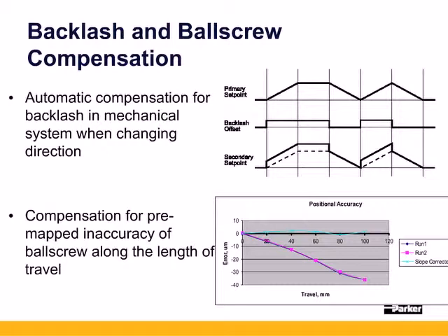So the ball screw profiler is a table for compensation for the periodic and linear errors, allowing higher accuracy positioning without the additional costs of linear encoders or the complexities of a secondary feedback. In addition, you also have the backlash compensation, which allows for hysteresis when reversing direction, such as belt-driven systems, gearheads, or non-preloaded lead screw systems. These are added to the primary set point, as you'd want this compensation done for any of your move types on the axes.